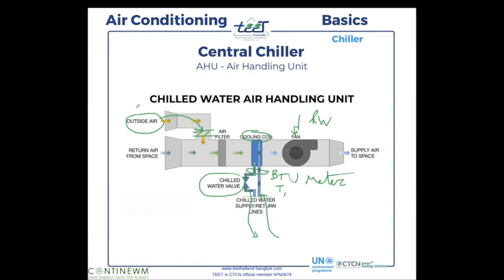And normally the fresh air is 5 to 20%. But we have to make sure that nobody will modify it during a proof of concept when we compare the performance, that the fresh air was the same. This is very important because it can have a very big impact.